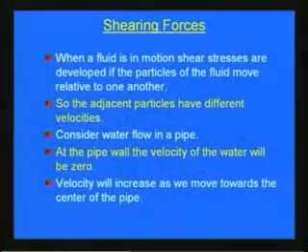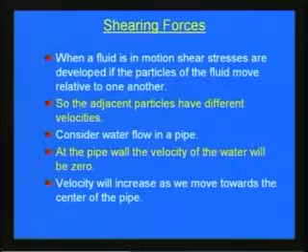Now, in the beginning we have discussed, say a fluid is getting deformed with respect to shearing forces. So, shearing forces are very important in fluid mechanics. So, when a fluid is in motion, shear stresses are developed if the particles of the fluid move relative to one another. So, since fluid is moving, you can see that with the layer wise there will be shearing stresses between the fluid, say if you consider a section, between the layers there will be the shearing force or shear stress.